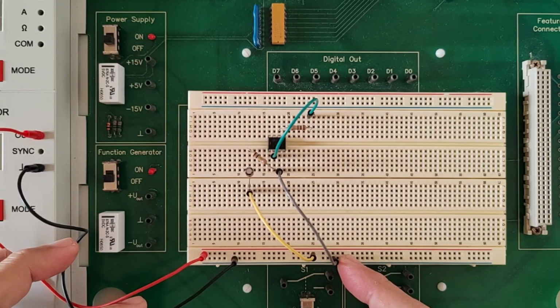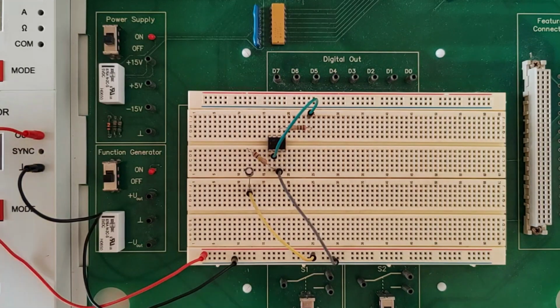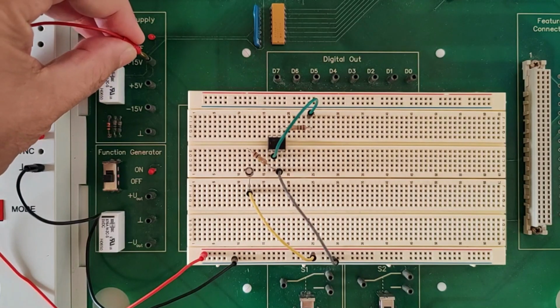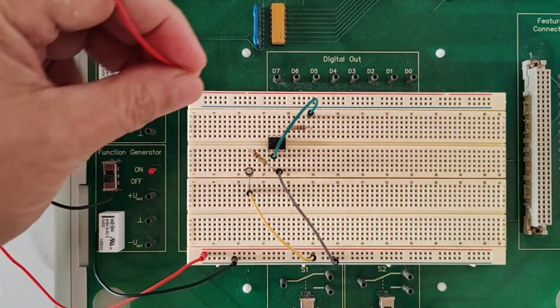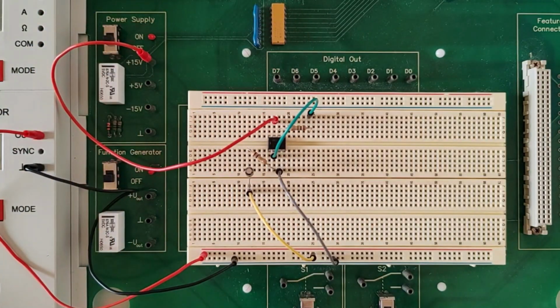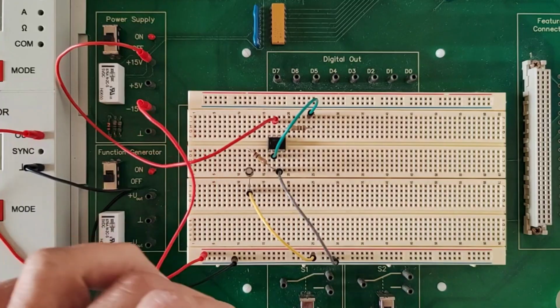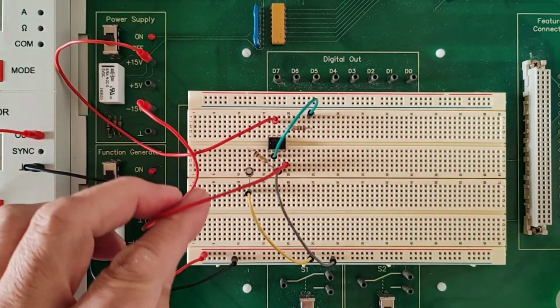Ground here. Now, what's left is the positive and negative power supply pins for our 741 IC, which will come from here: 15 volts and negative 15 volts. Based on the pinout on the schematic diagram we saw earlier, positive 15 will connect to pin 7. Let me connect it to pin 7, here. And negative 15 will connect to pin number 4. Here, the other side, pin number 4.